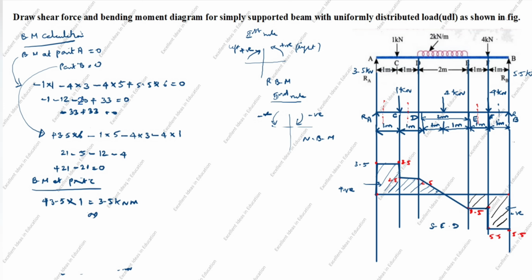Next we will calculate from here to here. You see this arrow comes down. Right side, the arrow comes down from here to here only. You see clockwise, and clockwise is negative. Minus 4 into the perpendicular distance from here to C only, which is 2. Next, we will take this arrow. You see the arrow comes down from here to here, which is clockwise. Right side we are seeing. Clockwise is negative, 4 into perpendicular distance. From here to here the perpendicular distance is 4.